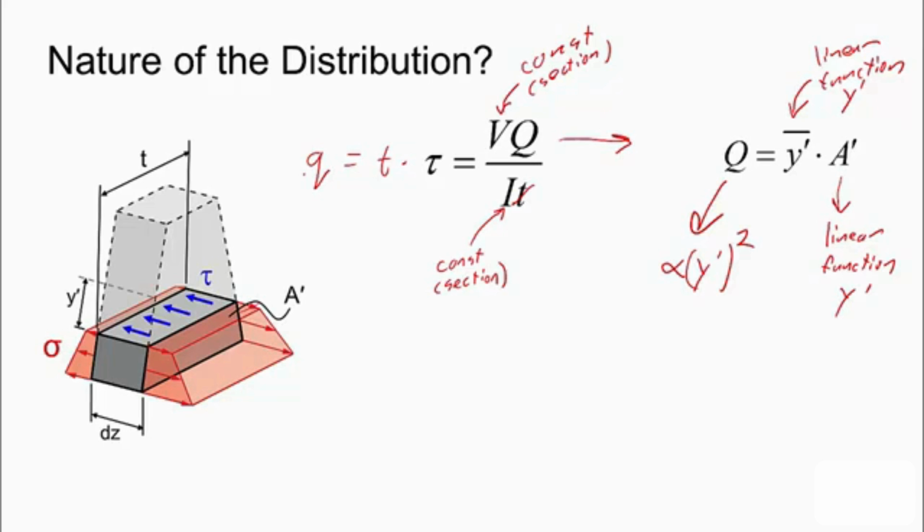And if we think about the fact that the shear stress reacts the imbalance between the two normal stress distributions, that also gives us an idea of where it will be maximum and minimum. If you had y prime equal to 0, you have all of the tensile stress acting on both sides, and so you create the maximum difference in resultant normal force.